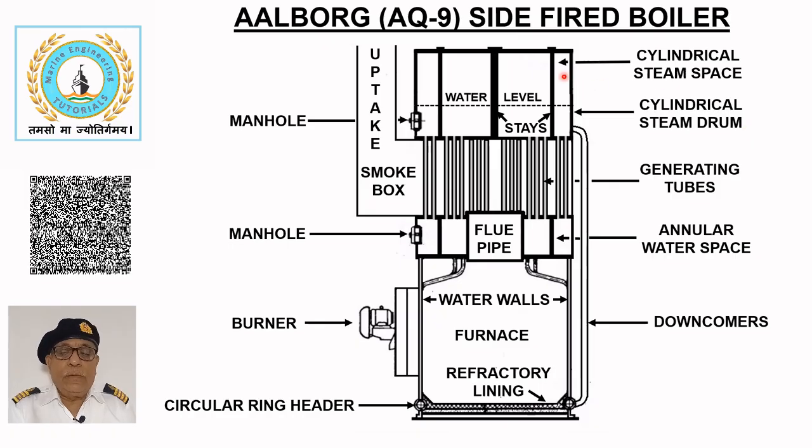Steam is separated and stored in cylindrical steam space above the water level. These boilers have a steam evaporation rate of 15,000 kg per hour or higher and can achieve steam pressure up to 16 bar, making them suitable for application on motor tankers.